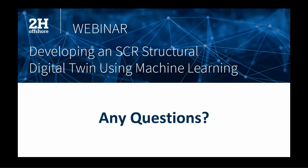Okay, the next question. If we already have an FEA model, why do we bother to train a neural network to replicate the same result? Machine learning does not replace the FEA work. The purpose here is more focused towards hotspot, load, stress, and fatigue real-time tracking. Essentially, the benefit is that we can use this for near real-time and life-of-platform integrity management using measured data, not merely a set of reduced sea states. As I mentioned, we can process 24 hours of data in literally a minute. So that's where you glean all your benefits.